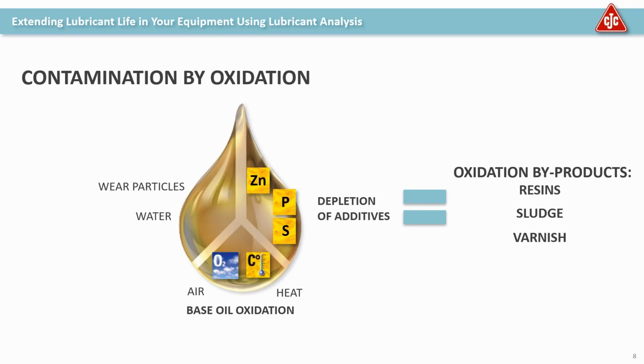It may actually be a clean ISO code by some standards. But as you look at this oil, in this case, is this going to last its full life? If you have water, as we discussed, if there's oxidation occurring, now you have a catalytic environment where the additives are slowly being depleted, and that can increase rapidly.